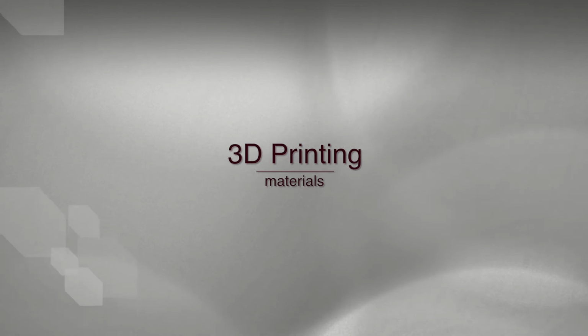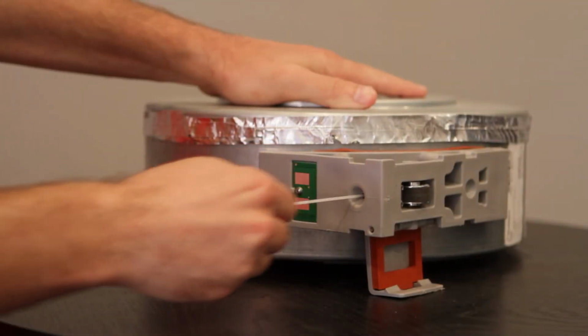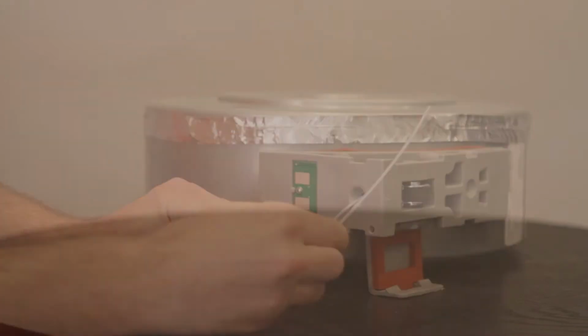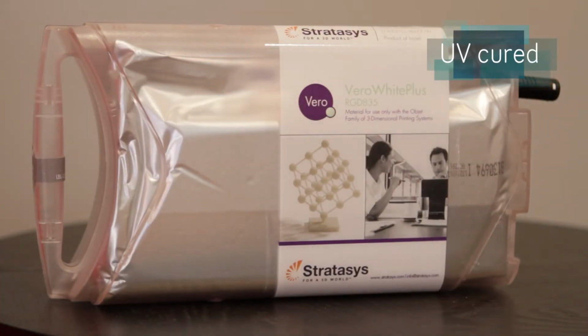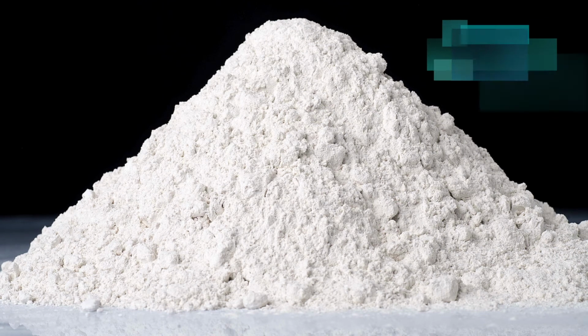Let's talk about materials. Most 3D printers work with one of three types of materials. They either work with a filament, which is melted and extruded to form the shape of the part, a liquid resin which is cured by UV light, or a powder that is infused with binder or sintered.